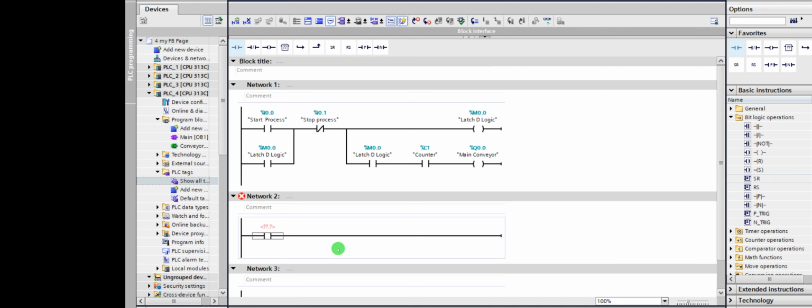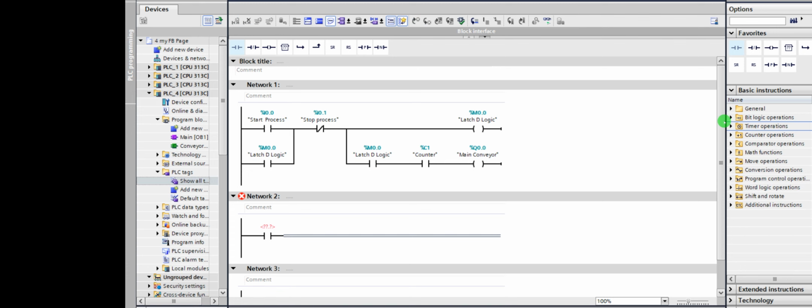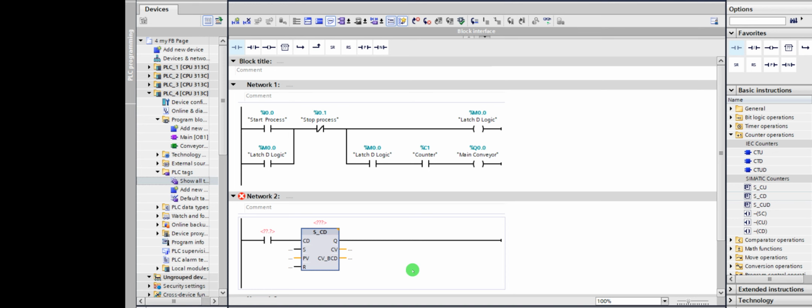All right, so if that is done, I'm going to also get that counter we are talking about, the counter device that will count the product from our instruction. So come back here onto our counter bit. We need counter count up. So it should be count down. Let's use countdown. We're going to count down the value. Now this is my counter, going to be C.